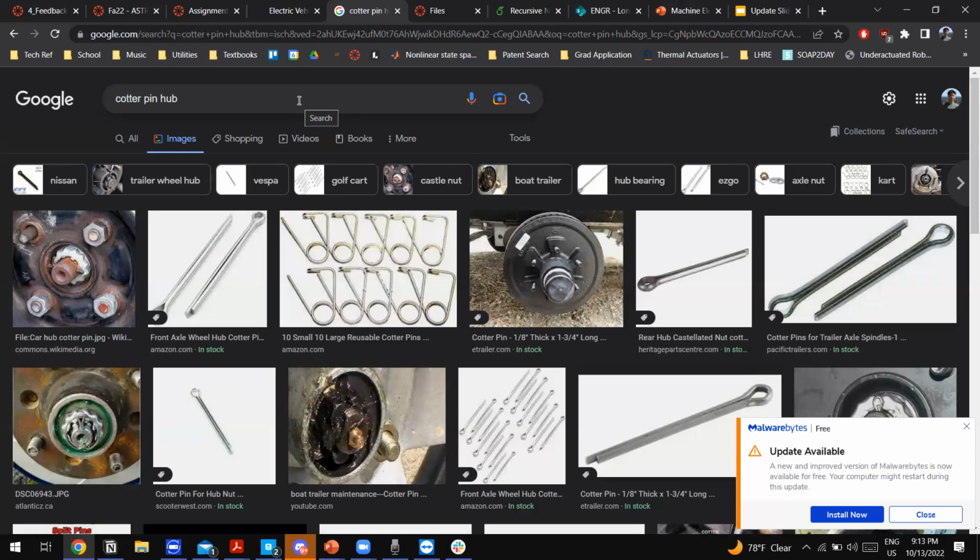I have one more question. What about determining the size of the thread on the hub this year? Like, the size of whether you want a smaller thread size or like... Oh, thread. I think the thread size is basically dictated by your bearing size, right? Oh, no, I mean the actual threads, like on the center lock, right? Yeah, I understand that. Your thread can't be bigger than the shaft that you put through the bearing, right? So it's driven by the bearing size. You basically make the thread as large as possible while still being able to fit it through the bearing.